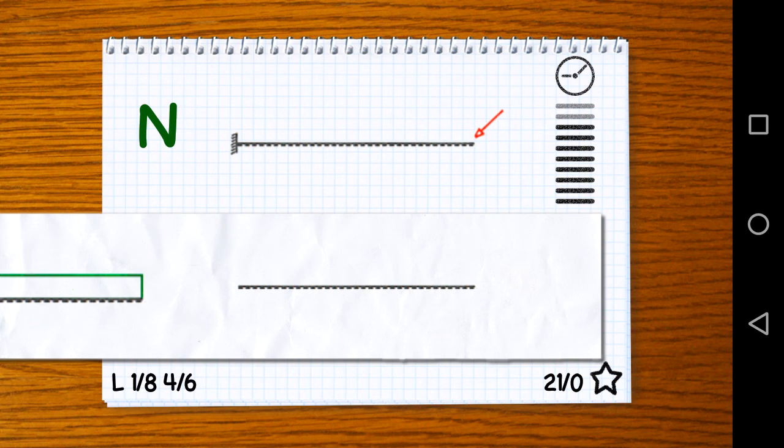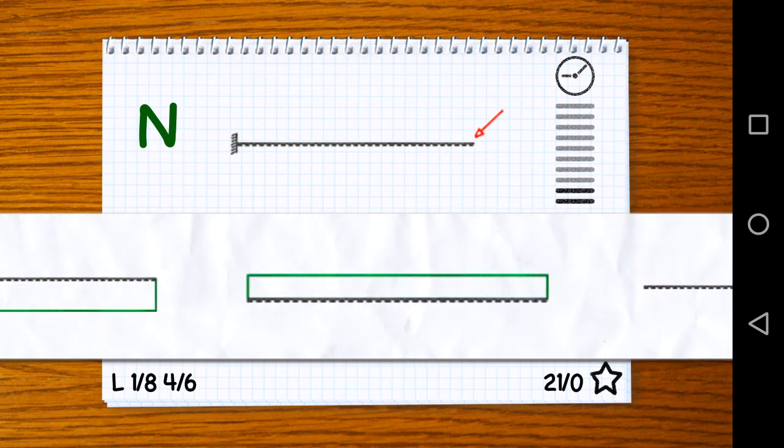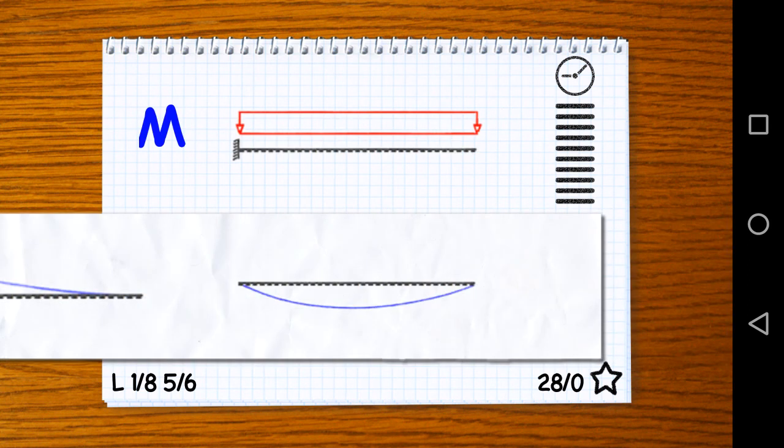What we have here is the same system as earlier, but now we have a single load there. That single load has some inclination, so we can split this load into 2 different directions, a vertical one and a horizontal one. How will the horizontal one be directed? It would be directed to the left, from the right to the left. So it's going to put the beam under compression. And we say that compression for a beam is a negative normal force.